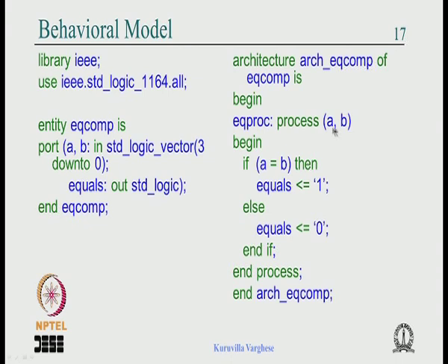When an event happens on the signals in the sensitivity list, we are talking about the simulator, the simulator will run from top to bottom, and whatever is written as description is computed from top to bottom once.